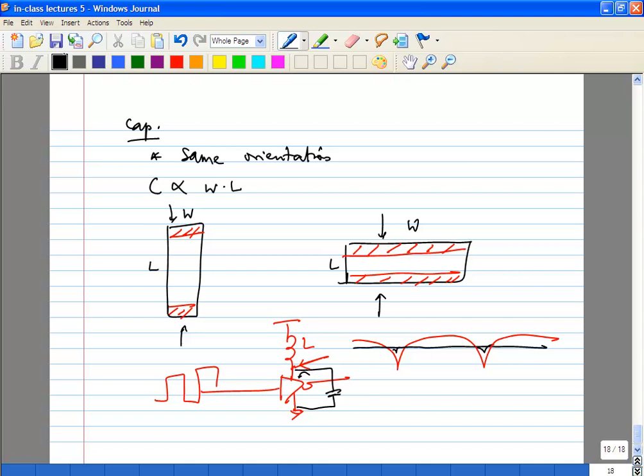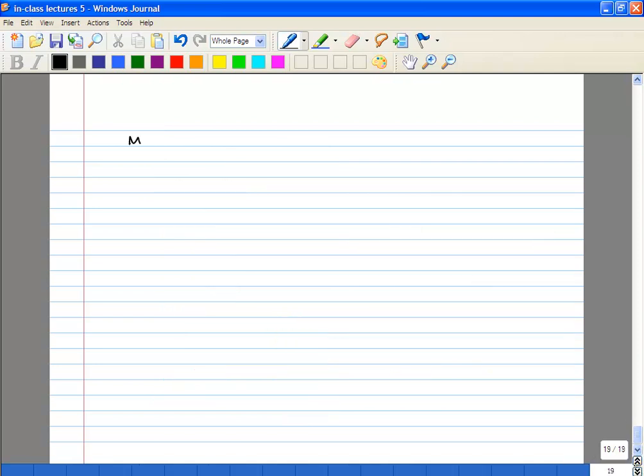Now you are basically relying on the fact that the capacitance is low impedance for that pulse of current. If you have some series resistance with that, you can be pretty sure that you are going to kill your decoupling. If you do a layout like this, it's a perfectly good way of killing your decoupling. Similarly, you can show the same thing for your MOS cap.